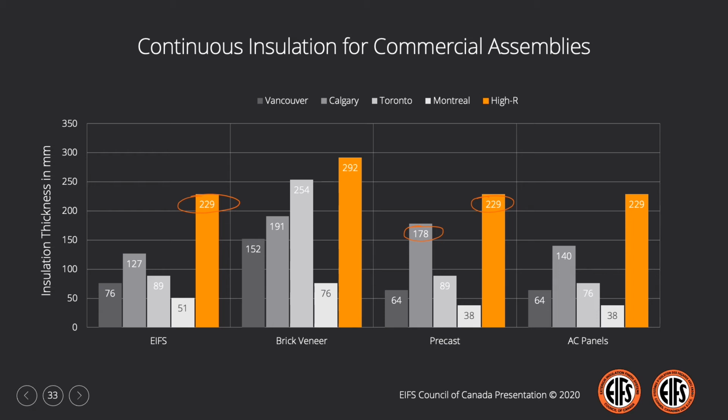For the high R, where we are exceeding greater than 8 inches of SPF, there's a minimum 12-hour cooling period required. It's not believed that these cooling periods were accounted for in the initial or upfront construction costs for the high R or the Calgary condition. It would appear in the costing tables that the difference in the high R relative to other locations is only a difference in the material costs and does not reflect the non-productive labor activities associated with cooling periods, mobilization, and demobilizations.